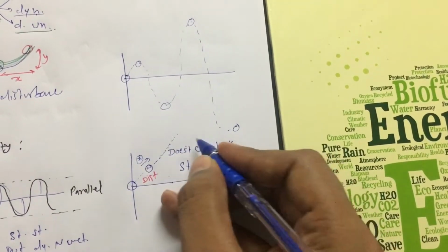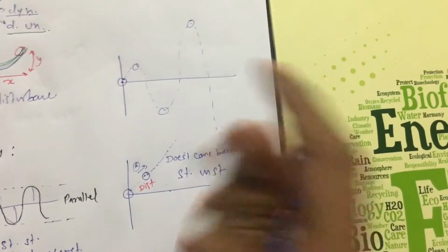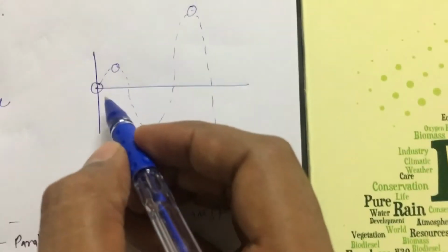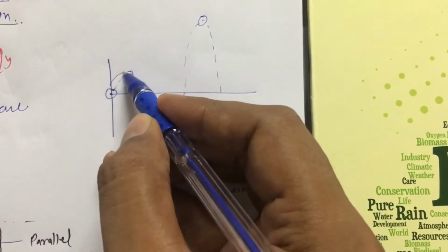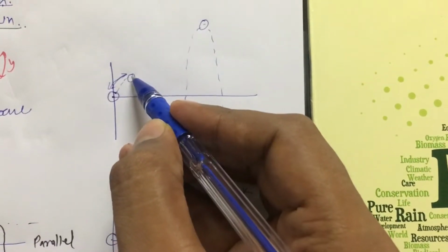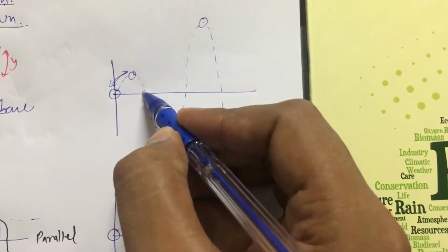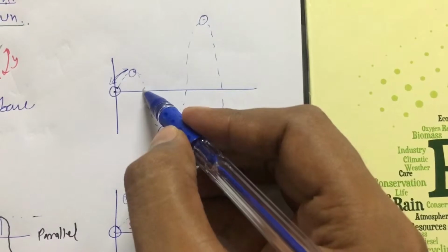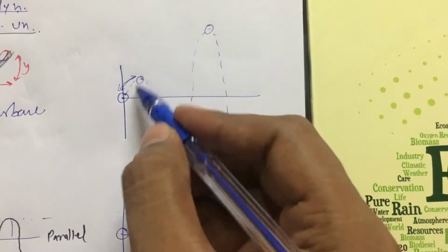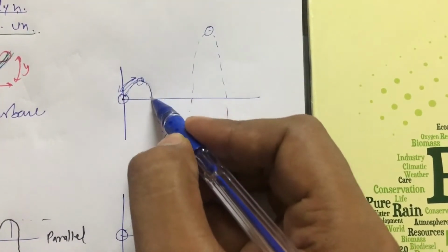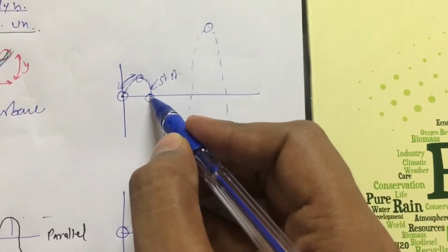Because this is statically unstable, we will not draw a graph at all to discuss dynamic stability. Now see in this case what is happening. The ball is here, and from here to here is the disturbance part. After that we have to discuss our nature characteristic. Displacement is decreasing. Okay, very good, so this is dynamically stable. But after that what is happening? Displacement is increasing with time, correct? Displacement decreased from here to disturbance, then after that it is coming to the mean position. So this is statically stable but dynamically unstable.